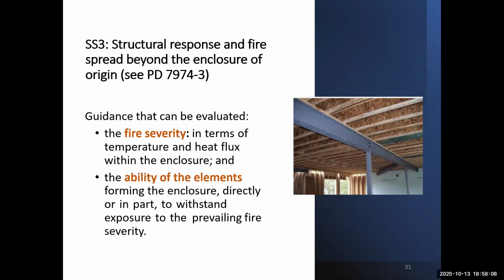We might find that if the steel beam is unprotected, it would lose its strength and show excessive deflection after only 15 minutes. This is a very risky phenomenon because it will lead to collapse and allow fire to spread vertically.